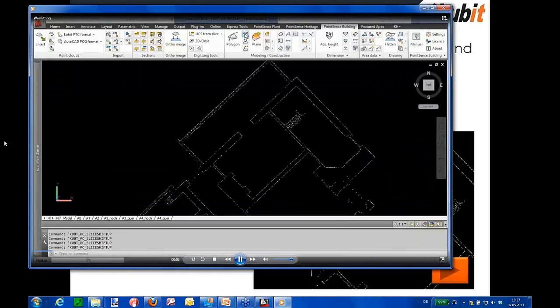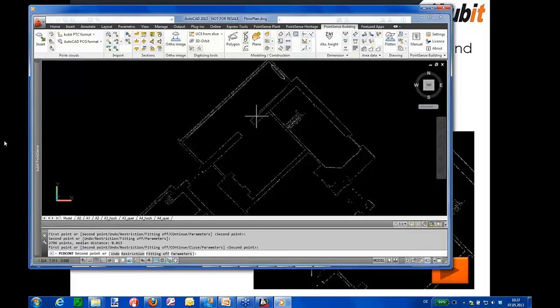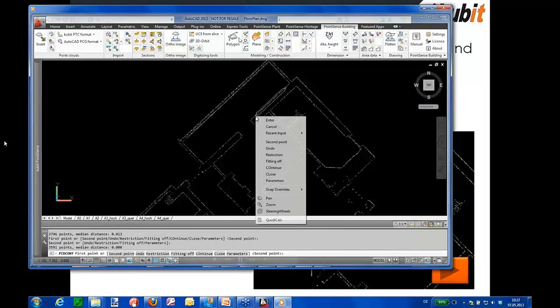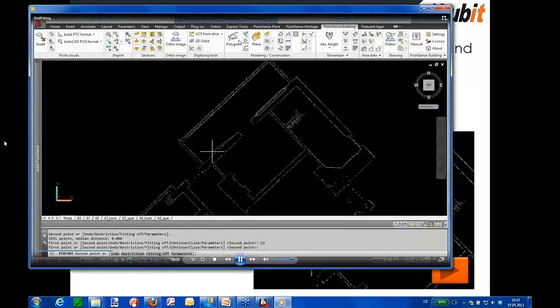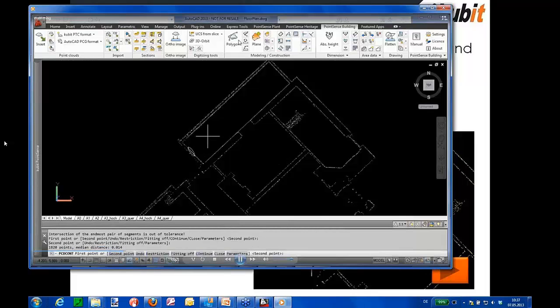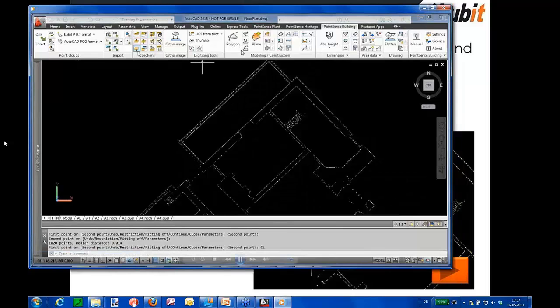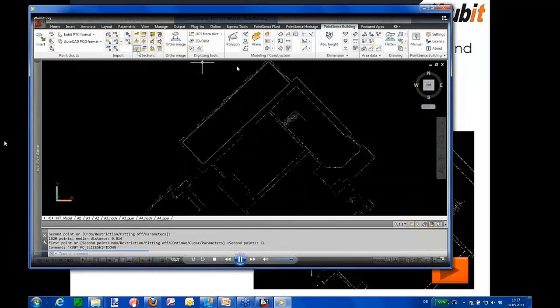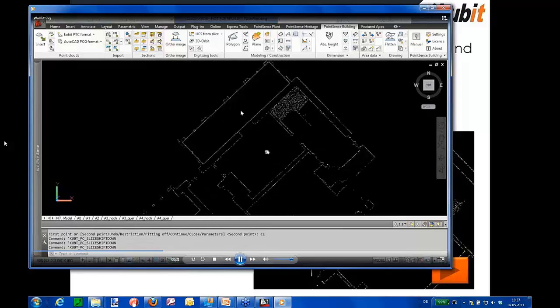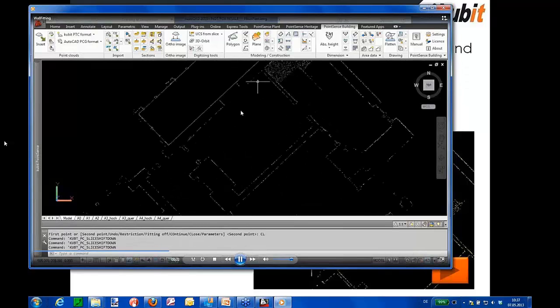At first the command is started, and then I always click 2 points on each wall. I don't have to click exactly on the trace, just roughly. It always takes a narrow region between both points, and from the points inside it calculates an average line. The lines are automatically extended to the room corners, and then I say close and have the room polyline. I'm doing another one.